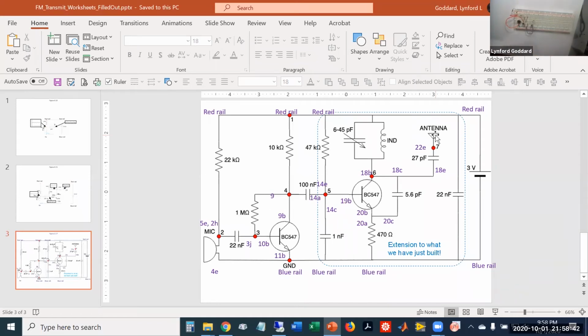And it looks like this wire is slightly too thick to fit in. So what I'm going to do is pull back a few of the strands so that this is a thinner object. So at the very tip, I have slightly fewer strands. I'm also going to twist it a bit more so that I can get a sharper tip to be able to plug into the protoboard. Let's try this again.